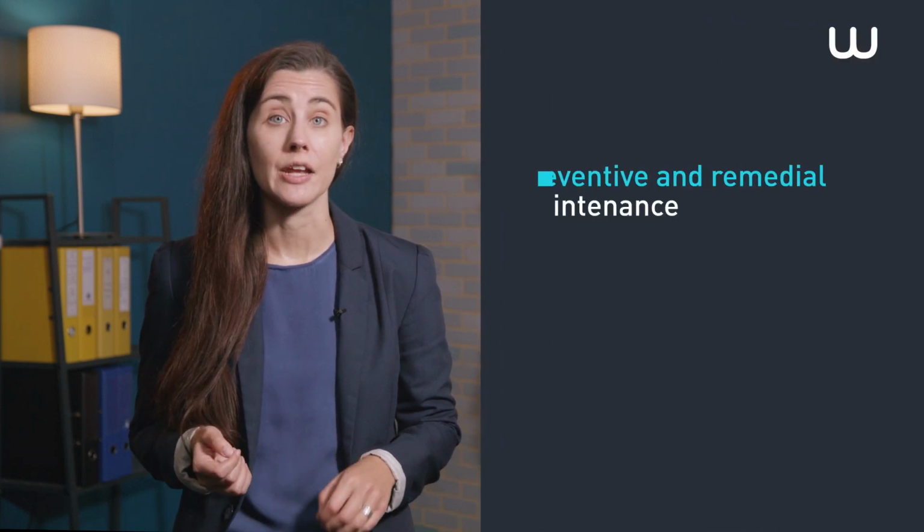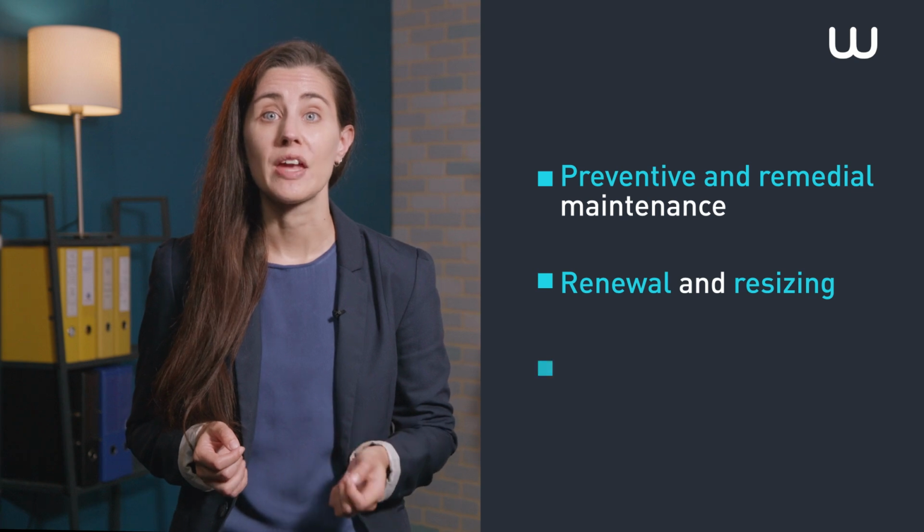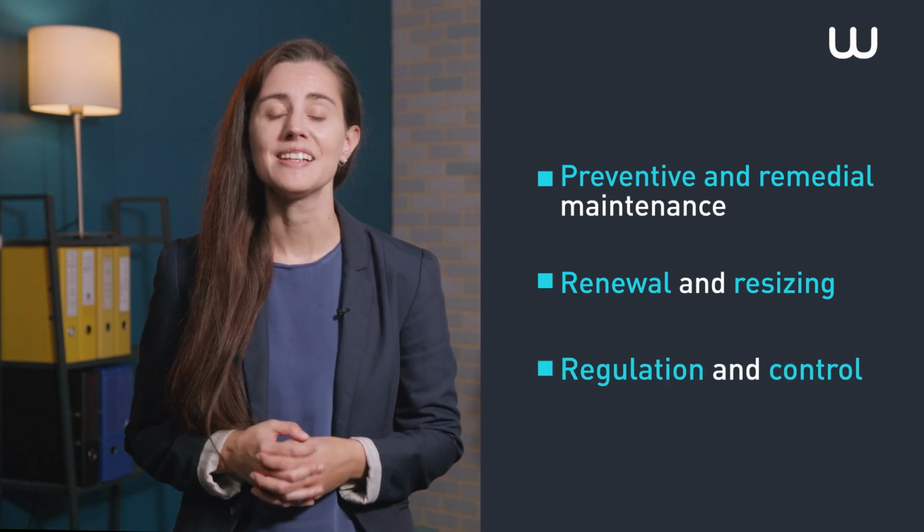The main points to be remembered. In order to optimize pumping facility energy consumption, various actions can be carried out with respect to preventive and remedial maintenance, renewal, resizing, regulation, and control at both a hydraulic and an electrical level.